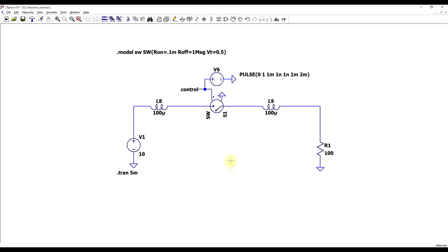So with this sort of setup, where you have considerable wire inductance on both sides of the switch, you can have a problem even if your final load is resistive. So in this case, rather than trying to suppress the spikes appearing over the load, or well, the wire, it's far more practical to try to limit the voltage that can appear on the switch.